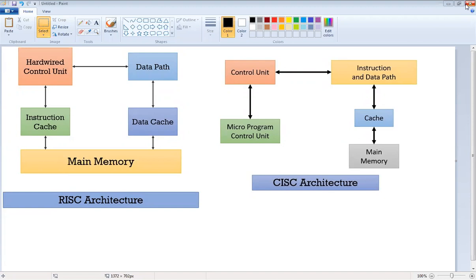In-system programming is available in the 8051 as well as the PIC microcontroller and the AVR microcontroller. Internal EEPROM is there along with your ROM, up to 4 kilobytes. Again, the RAM is not general RAM. It has static RAM, SRAM. We know that SRAM and DRAM, two types of RAMs, are there. So there is internal SRAM of 16 kilobytes. An external 64 kilobytes of data space can be given to the AVR.